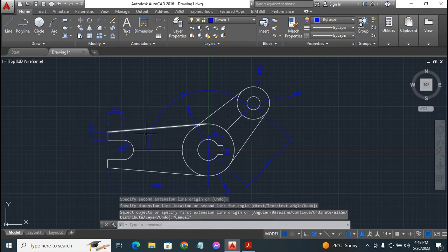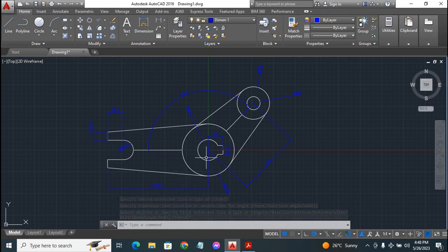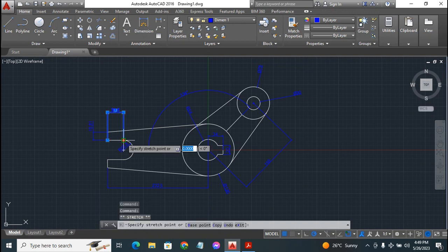Now if you take a look at the drawing, you see that some of the construction dimension lines are cutting across our main lines, and we don't like that. So in order to make some changes, we want to extend it out of this line. You can click on the actual dimension lines you want to change, then click on these small boxes; it turns red, then you can adjust up and down to any position you want.